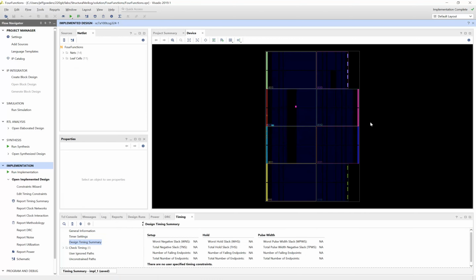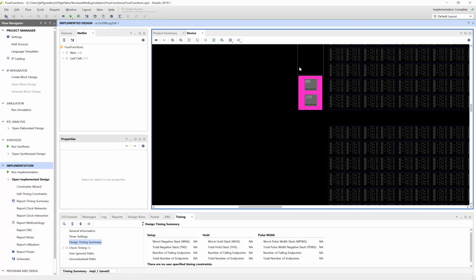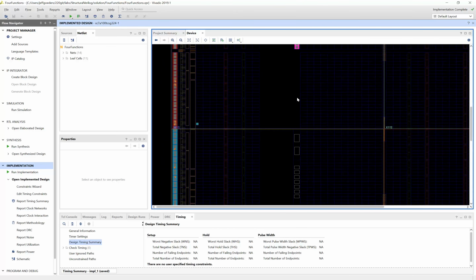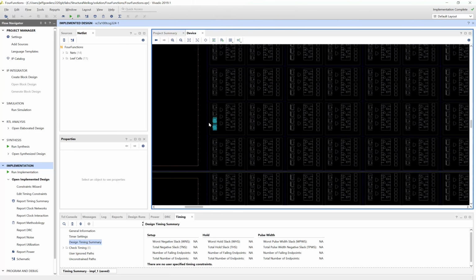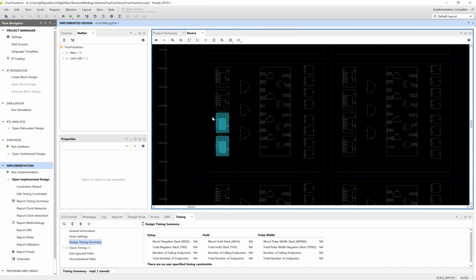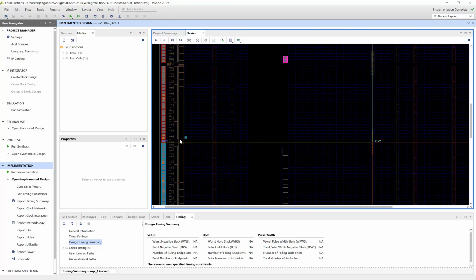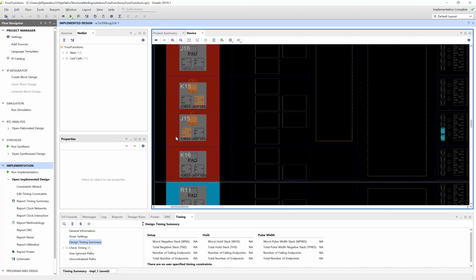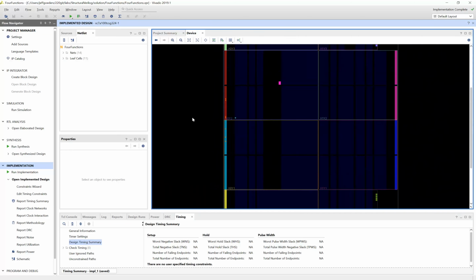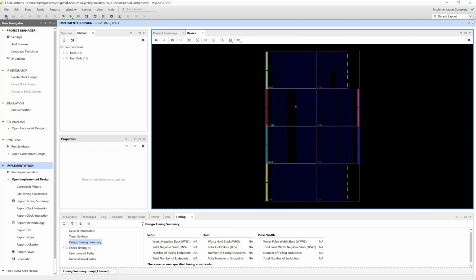And so you can see this is actually a large chip, and this small region in pink is, if we zoom in here, there's one part, these are input pads where signals are coming into our design, and if we zoom out, we can actually see a couple places here where there's actually the LUTs of our design being implemented on the FPGA. And finally, over here, there's some more input and output pads used to get signals in and out of our design. We can go and close the implemented design here in the top right.